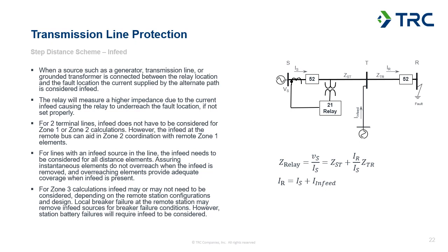So you really got to look at it from a perspective of both with the infeed being present and also with an outage on that. So if it was a generator, you may want to look at that, and you want to make sure that the relay is going to respond appropriately for both of those conditions.